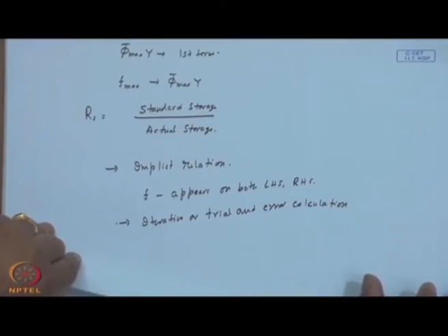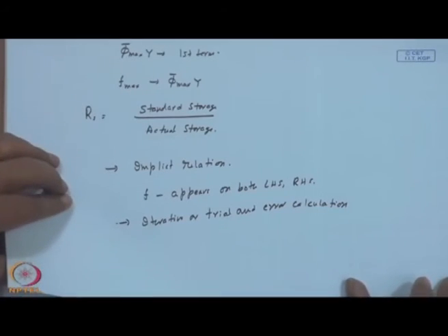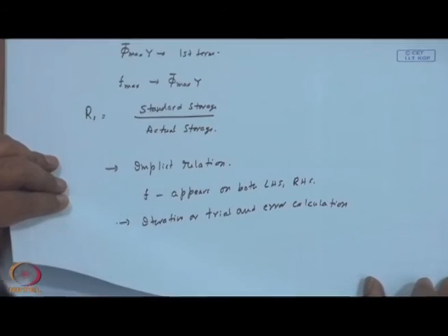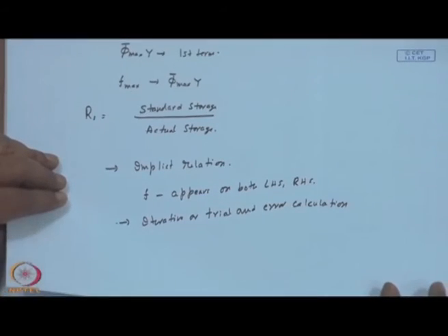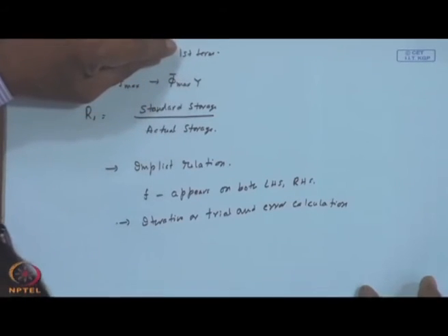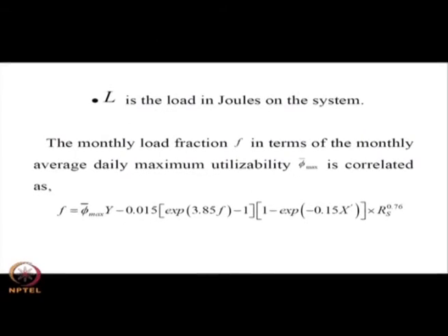So, compared to F chart, in addition to taking into account the minimum temperature at which energy delivery is desired, this relation is explicit, and we need to calculate yet not known to us the monthly average daily utilizability. Appears to be an exciting parameter, which comprises of the statistics of the solar radiation and the collector parameters and the operating condition at which the energy delivery is desired.